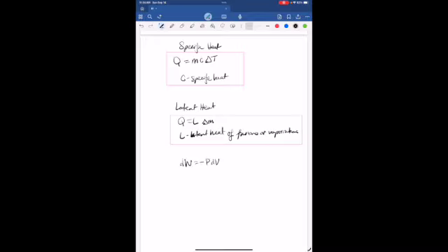We can integrate that to get the work equal to minus the integral from initial to final point of the pressure times dV. And you'll recall that we discussed that the work is process or path dependent.